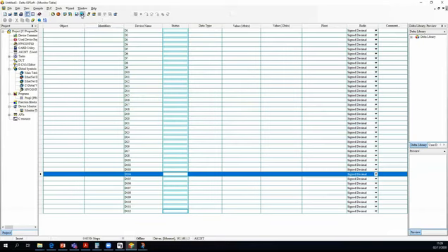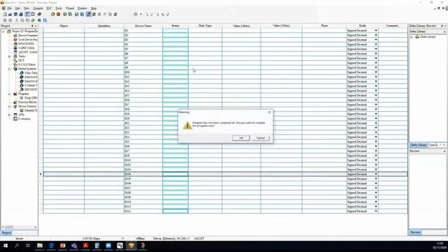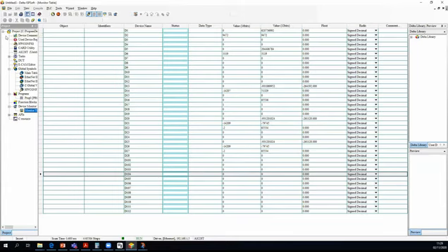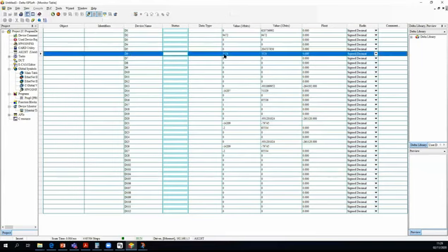Okay, so if everything is okay, then I will go online and I should be able to read all the different values that are coming from the drive, like the DC bus and status word and all of that. So you can see it here. In D6, I have the DC bus value of the drive. So that's 312.